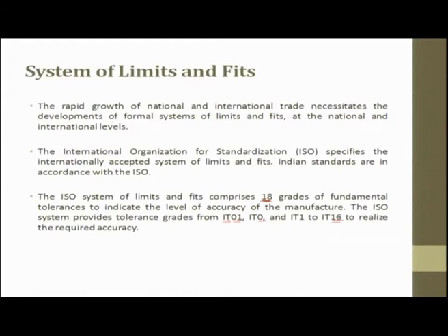So, rather than writing 0.004, 0.002, where there might be a typo or some error, this is replaced by a grade, IT01, IT0, IT1, or it can be ITXX. People will look at the ITXX value and understand that this is the tolerance they have to maintain. So, we can avoid mistakes and realize the required accuracy.